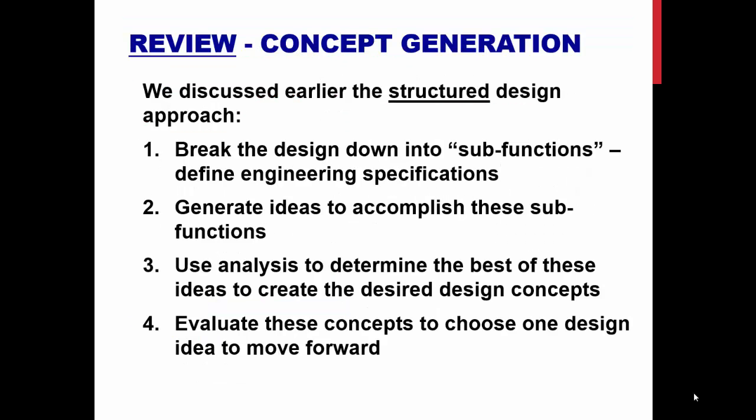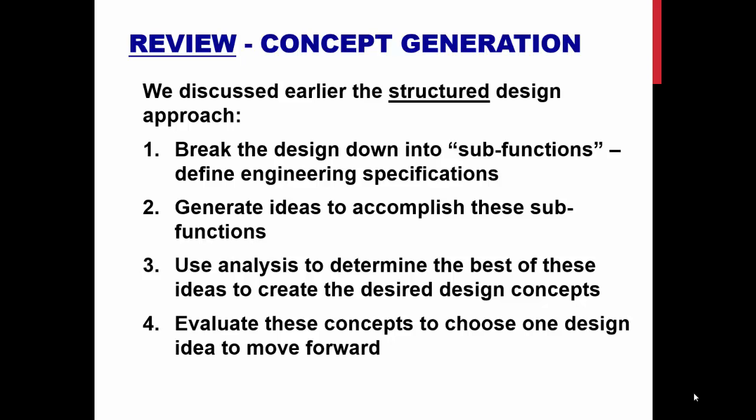So in review, looking at concept generation, we have been discussing using a structured design approach and breaking this design down into sub-functions so that we can design specifications for those, and then generating ideas to accomplish these sub-functions using things such as morphological matrices and pugh charts, then using analysis to help determine the best of these ideas in order to create the best desired design concepts that we can put together, and then evaluate these concepts to choose one design idea to move forward with.